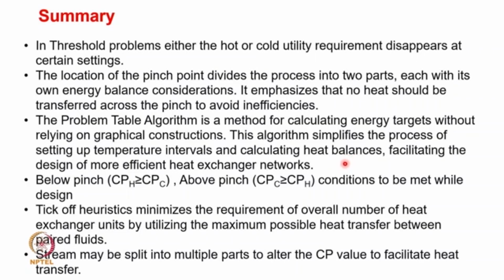The below pinch and above pinch conditions have to be met, the CP conditions basically, while designing. And lastly, we have to use tick-off heuristics that minimize the requirement of overall number of heat exchanger units by utilizing the maximum possible heat transfer between the paired fluids. And a stream may be split into multiple parts to alter the CP value to facilitate the heat transfer.